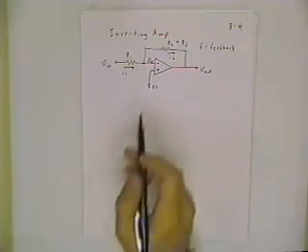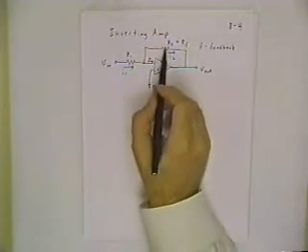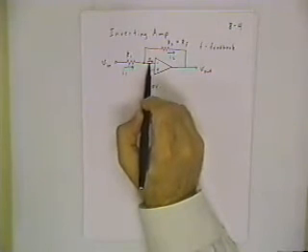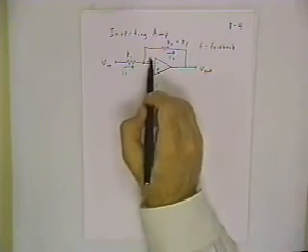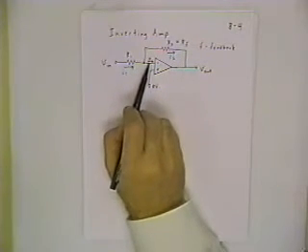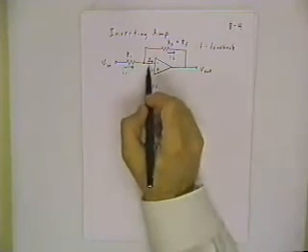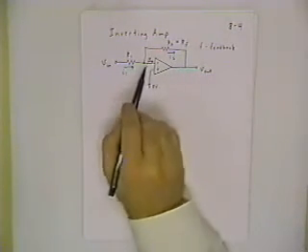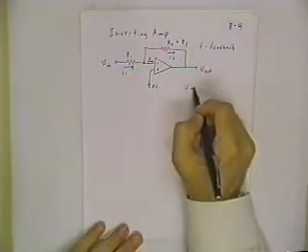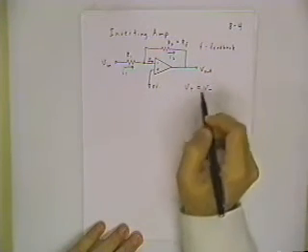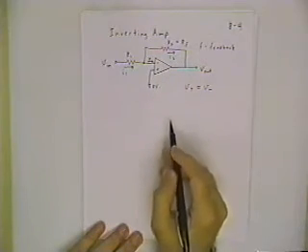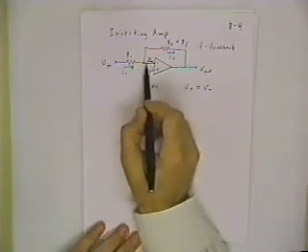And that in reality would be a few microamps, but compared to the milliamp level currents, it's so much smaller in a real circuit than the other currents in the circuit that we can effectively approximate it as 0. But for ideal model calculations, you just go ahead and assign 0 current to that wire and 0 potential difference across the inputs. Remember, these are the ones that I was calling V1 and V2 in the other drawing. So now we can say, ideal model says V plus equals V minus if those are the node voltages at the negative and positive inputs. We've already included the 0 current.